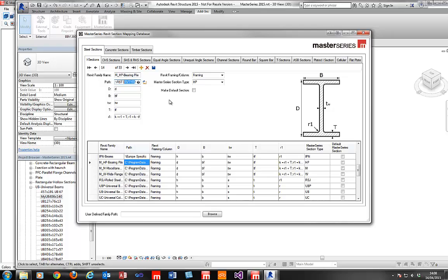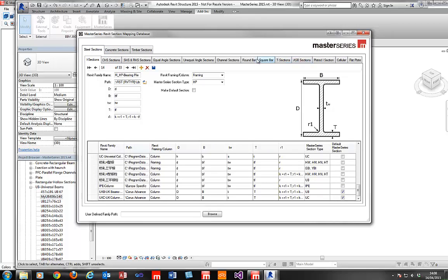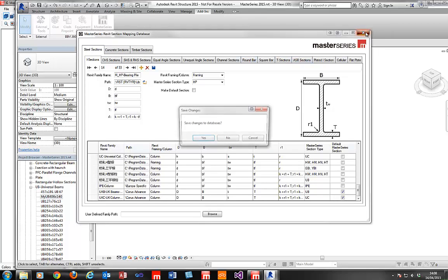Here we have RVTY year, which means that if we're using this in Revit 2015, that will be 2015, and in Revit 2014 it will be 2014. So you don't need separate databases for different year versions of Revit. Also, you can simply go down in this open database and add your own library or your own family with your own parameters here. So it is very extensible, and it is certainly going to be a much more extendable and comprehensive system for Revit family mapping moving forward.